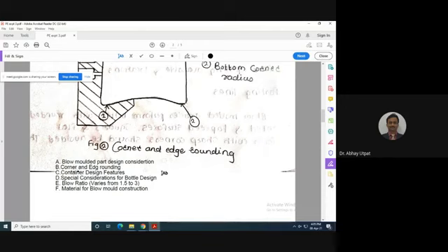Wall thickness uniformity is also checked. Then deflection rate, label consideration. The last one is hot fill capacity. Hot fill capacity means some hot drink is filled in that bottle, maybe hot water or hot oil, and then how it behaves, whether it shows any leakage or deflection due to the hot liquid, all such cases are checked.